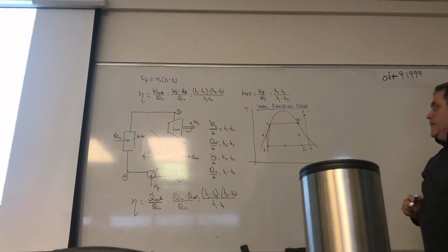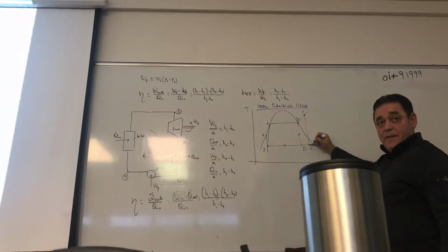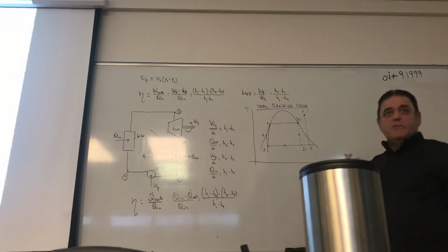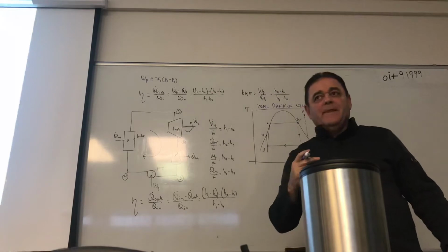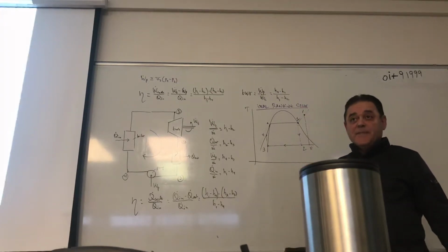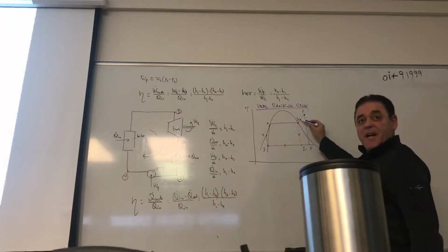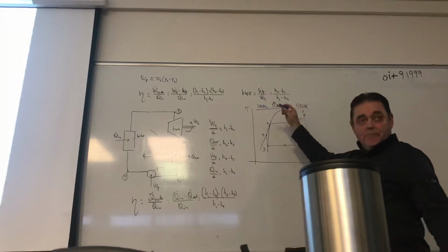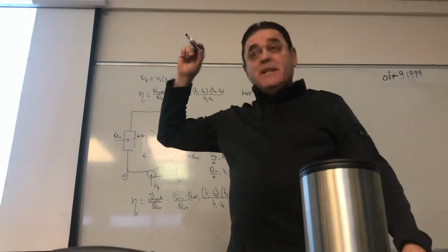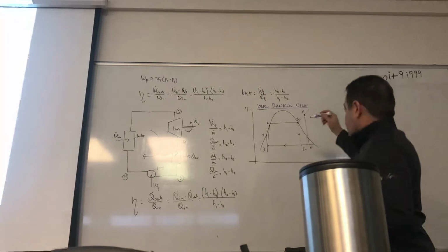I have a higher X value here, a higher quality, which means fewer particles. But there is another fringe benefit, which is higher efficiency. Why do we get higher efficiency? Because the temperature of heat addition has been pushed up. Remember from the Carnot efficiency, 1 minus Tc over Th, as Th goes up, you get better efficiency.